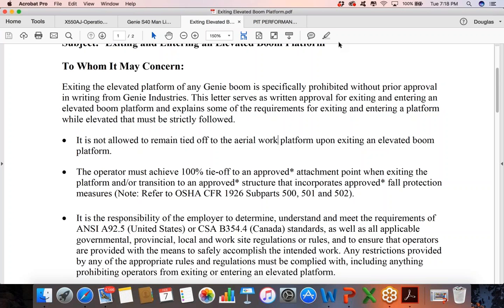And then also high top leather work boots. So we want to make sure that we're not wearing safety shoes, we're wearing safety boots. I tell employees all the time, especially for steel erection or anybody who's on the roof, I really want them in lace ups. Although then you may have to have a metal tarsal foot protector in place to make sure that no slag or anything gets into the laces if they're doing hot work. But I'd much prefer to have them in lace up boots so they have adequate ankle protection and that the boot is snug.